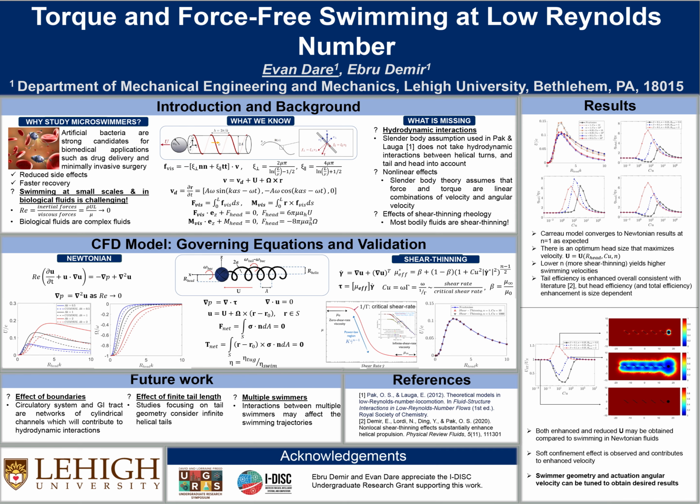CFD model, governing equations and validation. Newtonian. To accomplish this, we will first validate our simulation for the Newtonian case. When we non-dimensionalize the Navier-Stokes equation, the terms including time as a variable are scaled by the non-dimensional Reynolds number, which is the ratio of inertial forces to viscous forces.